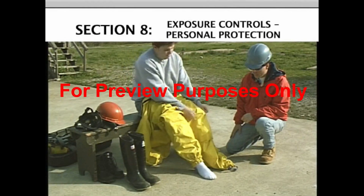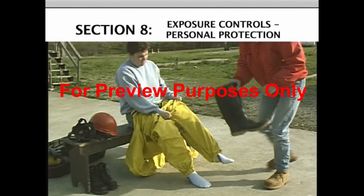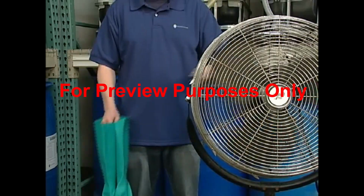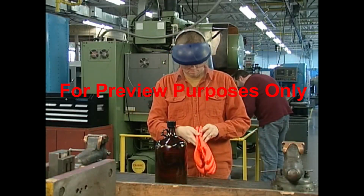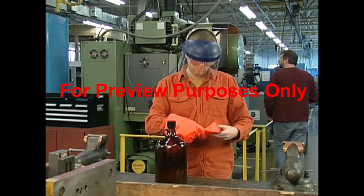Engineering controls, personal protective equipment, and exposure guidelines are addressed in Section 8 of the SDS. Engineering controls might include things such as the use of local exhaust ventilation systems when working with a material. Recommendations regarding personal protective equipment focus on minimizing the risk of exposure to the material.